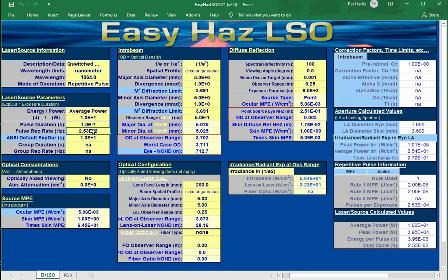Let's go to 2,531, hit that, and you'll notice that's the crossover frequency between 2,530 and 2,531. When we make that 1 hertz step, it switches to Rule 2. That's the crossover frequency for this particular analysis, and that's what crossover frequency really means. What's that frequency where we change from Rule 1 to Rule 2, or Rule 2 to Rule 1?